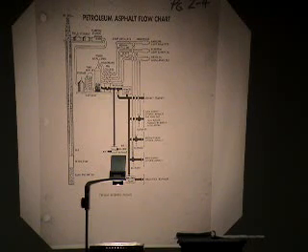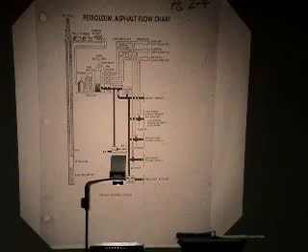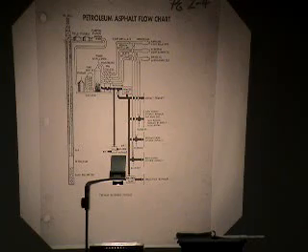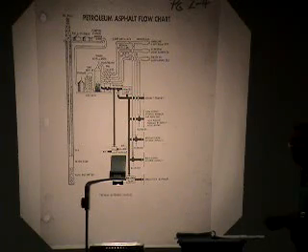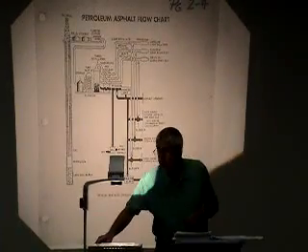And you say, well, you can't mix water and asphalt. And you're right, you can't pour asphalt into this cup, pour water in it, and mix it together. You can't do it. With that emulsion plant, there is a special process in which they encapsulate the asphalt binder molecules with the water, and then when it's sprayed out on the road, that water will evaporate and leave the asphalt binder in place. But that gives you an idea of how we come about getting our asphalt binders from our crude oil. Any questions on that?